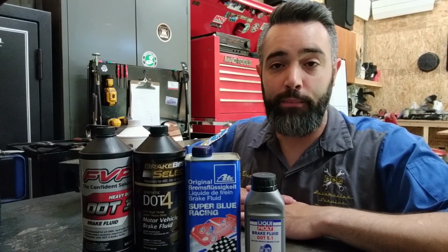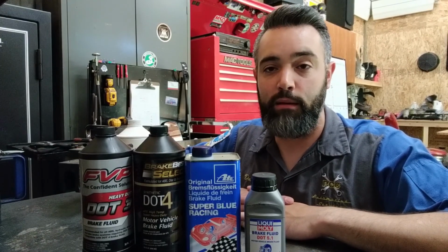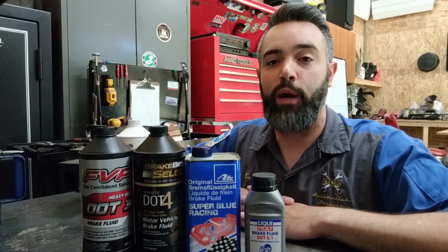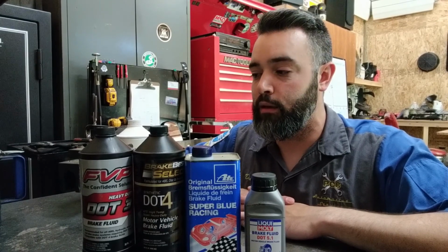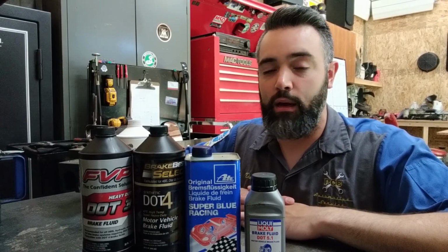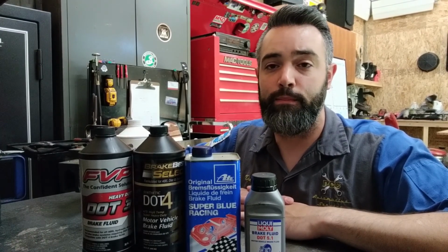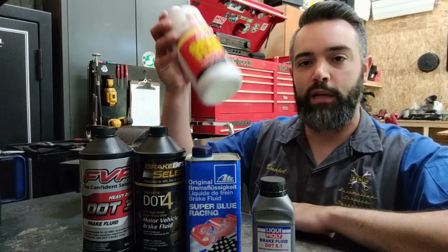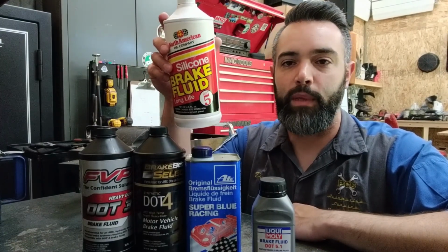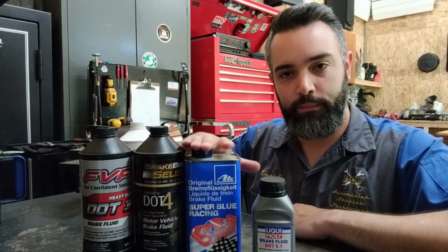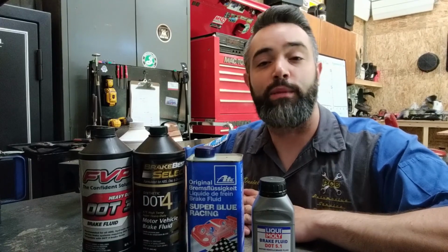There are many people who do choose to do their own maintenance, and part of that maintenance, people like to do brakes. They seem simple enough, but the more you understand about brake systems, the more complicated they are, and they are the number one safety item on a vehicle. So it's possible that somebody may not understand the differences between some of these fluids and introduce the incorrect fluid to the system. If we were to introduce a silicone-based fluid or a mineral oil fluid into a system that is designed for glycol, that could potentially cause the seals in the system to swell.